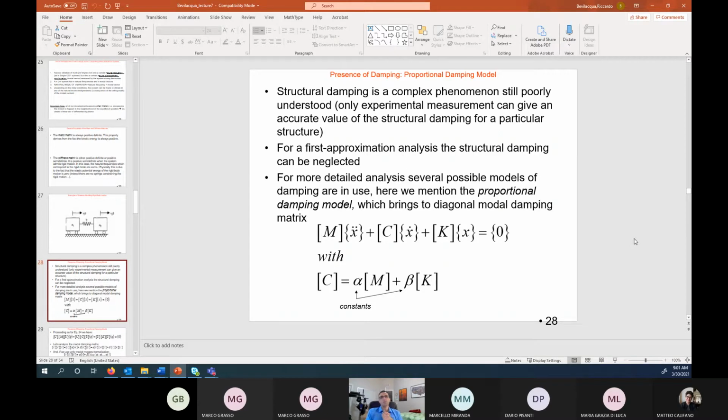And it kind of makes sense. A system is usually damped in different ways depending on its inertia, the mass matrix, and its flexibility, which is the K matrix. But really, it boils down to experiments. And this is true for problems like tribology, like modeling of friction. We still are not able to model friction that well, and so we base our models on experimentation. The field of friction modeling is still pretty active. So this is a similar scenario where we have a phenomenon that is not completely well understood.